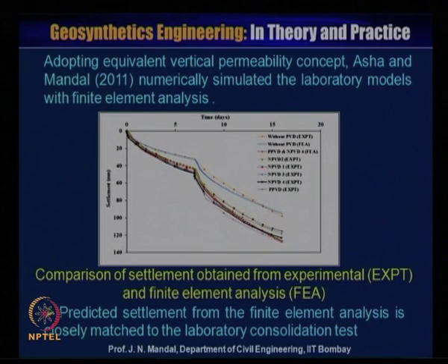Adopting the equivalent vertical permeability concept, Asha and Mandal 2011 numerically simulated the laboratory model with finite element analysis. This is the comparison of the settlement obtained from the experiment and the finite element analysis. You can see here the time versus the settlement for various prefabricated vertical drains.